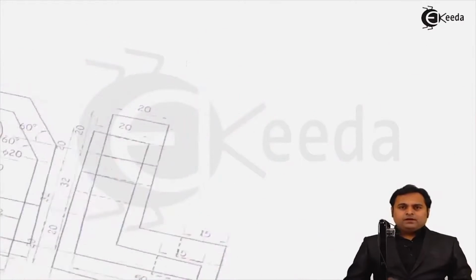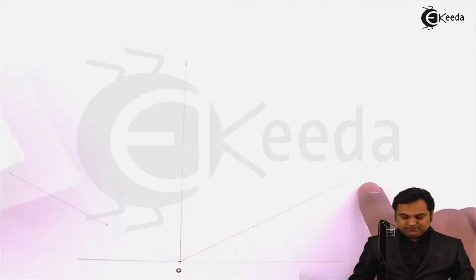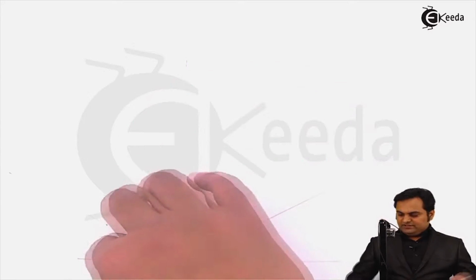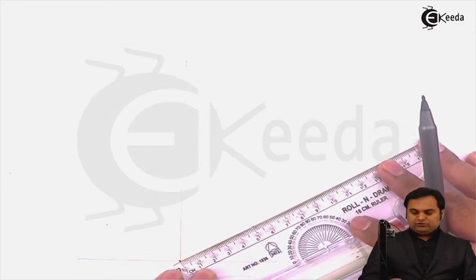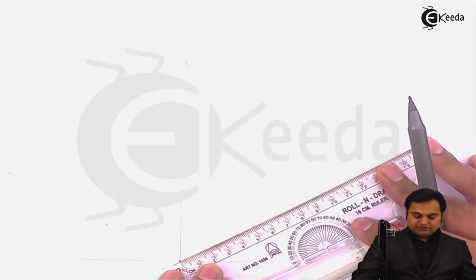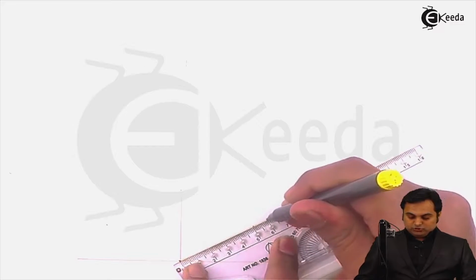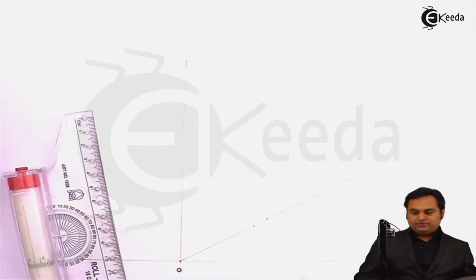in the problem, they have given the origin in the front view, as I can see here, and even in the side view. Origin is that point which is close to the observer, or we can say the reference point. So in this diagram, here will be the origin. This is the origin for us. And now when the object is kept on the origin, like if I lift it from the front view, and when I'm keeping the front view on this side, then origin is here and length should be along this line. So the length of the object will be marked here, height on this side and width over here.